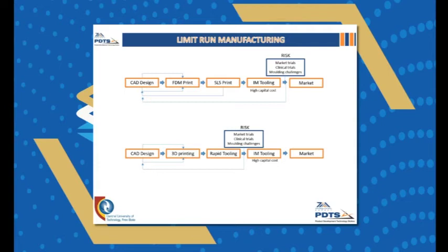If you have completed your CAD design and you are happy with it, you can then move on to an SLS print. This is where you would prototype a working prototype of your product. This you can use to show your client, or as a client, you can show this to investors for possible funding. If you receive funding or you are satisfied with the product, you then have to move on to injection mold tooling. And as I mentioned, this is where the high cost lies.